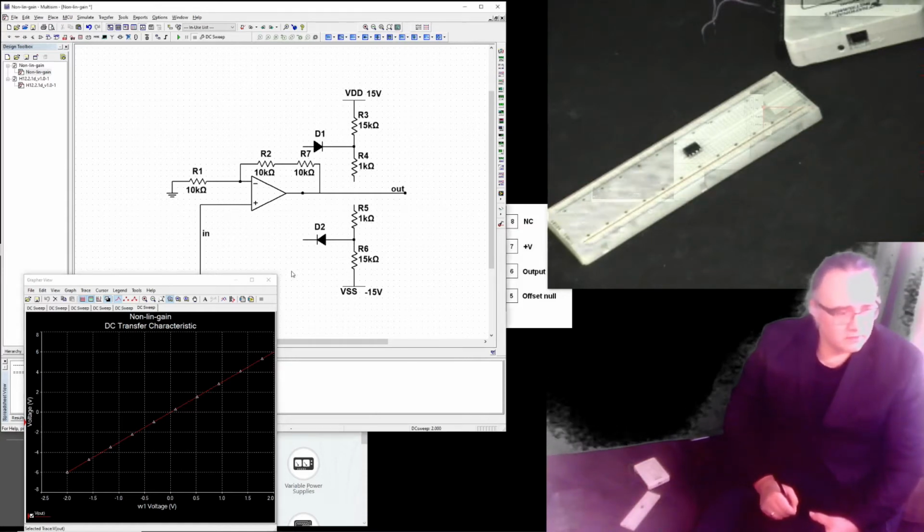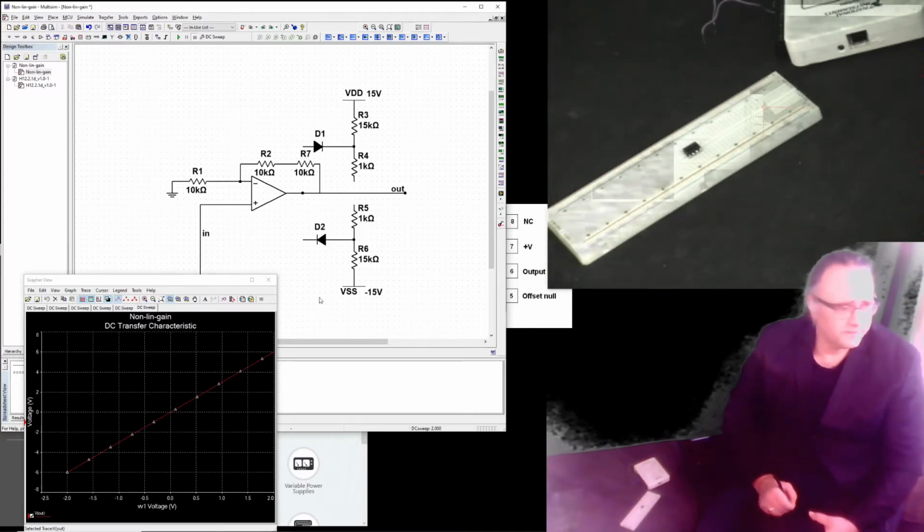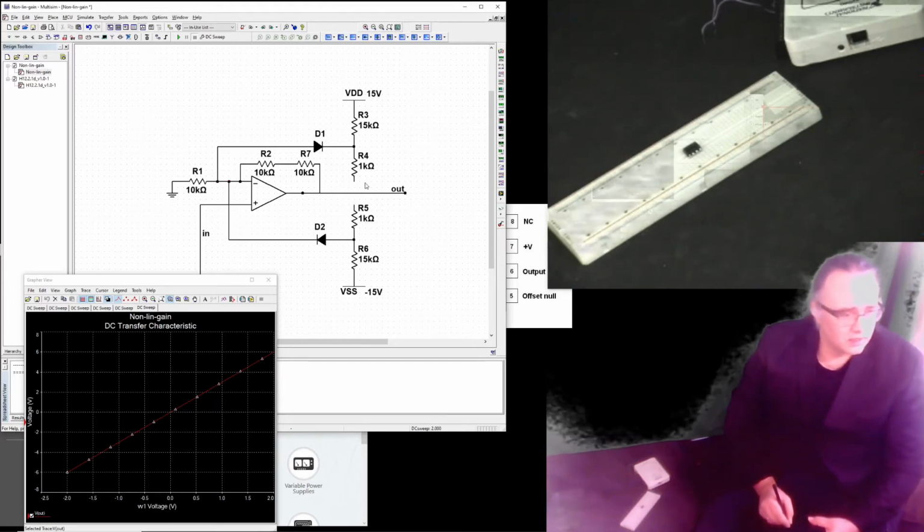Now, if I want to have nonlinearity in this transfer characteristic, I need to realize certain clipping. And this clipping can be done through these diodes. So basically, if I connect the diode, let me see, here at this point, and this in this point, and then this here and this here. Now the clipping network is activated.